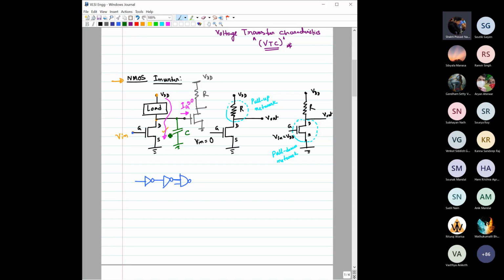This capacitance is also sometimes referred to as CL, or the load capacitance. Now, here I have mentioned this load, because you can replace this load with something else. You can consider the load as a resistance, a resistive load inverter. Eventually you can connect one transistor here, and how to connect it and all these things, if you know, fine. Otherwise we are going to discuss those things in much more detail, so we'll see there. As of now, let us consider a very simple case, only this resistance. So our total circuit then turns out to be something like this. The second case, this circuit only.